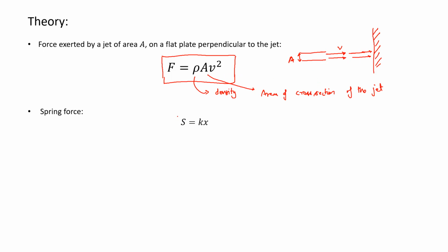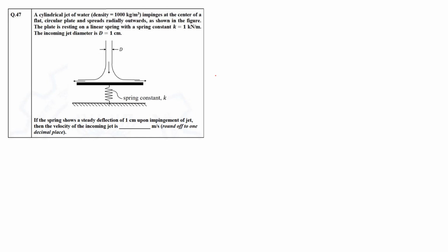And this, I guess everyone knows. So this is spring force. Spring force is given by just the product of the spring constant and the deflection in the spring. So basically S is proportional to the deflection, and then this spring constant comes in, and then you have the restoring force of the spring given by S is equal to kx. That's all. So these are the two forces at play in this question. And so once you know this, then I guess this is just a matter of doing force balance. And yeah, just try to see this.